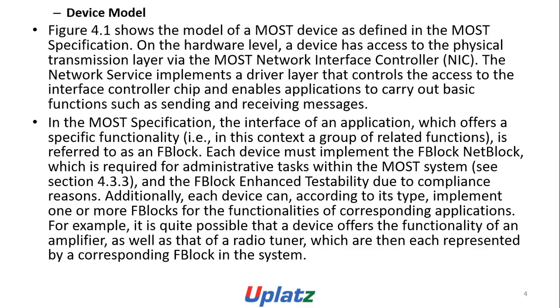Device model. Figure 4.1 shows the model of a MOST device as defined in the MOST specification. On the hardware level, a device has access to the physical transmission layer via the MOST network interface controller. The network service implements a driver layer that controls the access to the interface controller chip and enables applications to carry out basic functions such as sending and receiving messages.